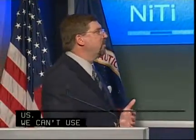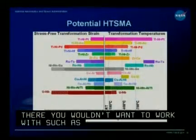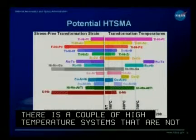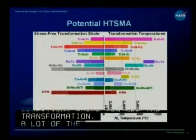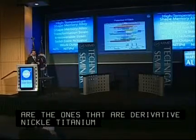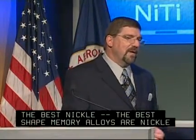If you look at the list, there are a number of material systems that you wouldn't want to work with, such as the uranium-based ones. There are other systems that are not microstructurally stable. There are a couple of high-temperature systems that are not environmentally stable under the conditions where you see the transformation. A lot of these materials are not processable, so if we start eliminating systems, about all you're left with are the derivative nickel-titanium alloys. And why not? Why not stay with what got you here? The best shape memory alloys are nickel titanium, so you might as well work with a derivative structure.